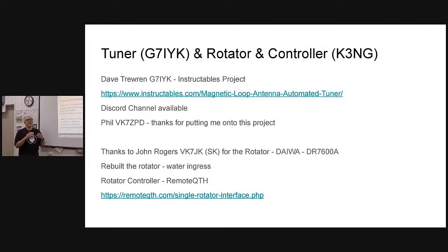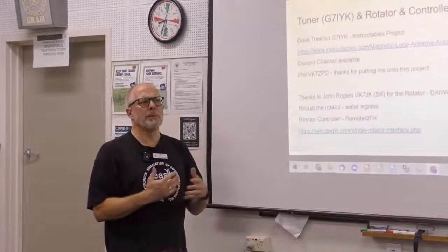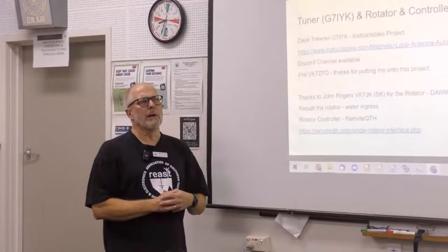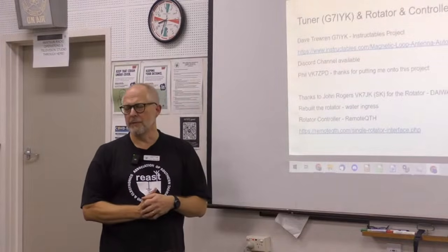And at the lower frequencies, it is radiating in all radiation angles. Straight up and straight down. So for a good DX antenna, you're wanting low angle radiation in the direction you want. Well, you get it, but you get it in all other directions as well. And you also pick up in all other directions as well. So there's a balance. You've got a bit of directivity, but yeah, I don't know. I don't have enough experience.